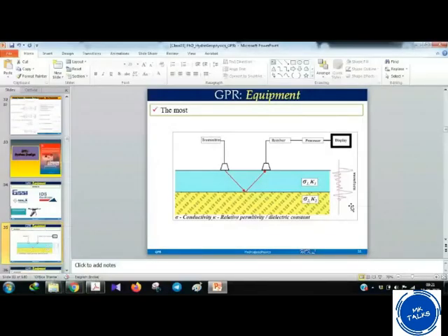What do you mean by stacking? We are generally sending pulses here, and a single pulse is not what gets recorded. I'll define it here. Say 32 stack: that means you will go 32 times and it will be summed. After summing all the data, it becomes more properly visible. So that is called stacking. Remember that.